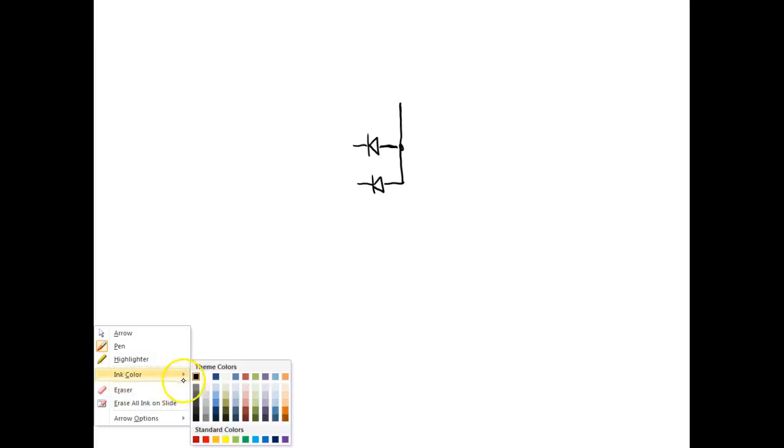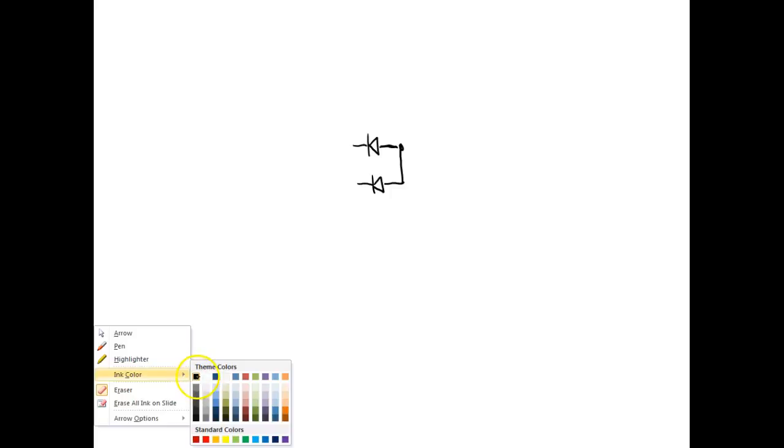And instead of a resistor that pulls it down to ground, I'm going to put a resistor up here that pulls it up to voltage. A resistor that pulls down to ground or common, we call a pull down resistor. One that connects up to power or voltage, we call a pull up resistor. Does that make sense?